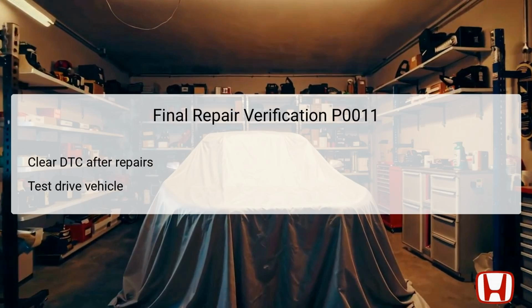Once all troubleshooting steps are complete and any faulty components have been repaired or replaced, it is critical to verify the success of these repairs. Begin by clearing DTC P0011 from the PCM using a diagnostic tool. After clearing the code, it is advisable to conduct a test drive under various conditions to ensure that the vehicle is performing correctly and that the DTC does not return.